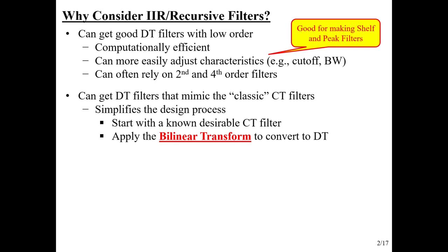And beyond that, they don't really do anything. So we have to be careful. And this may be a case where you bump up the sampling rate just by a factor of 2 or 3 or so to apply a filter without that kind of boundary or barrier of Fs over 2 getting close to the audio range. That might be overkill, but it certainly is something that can be done.